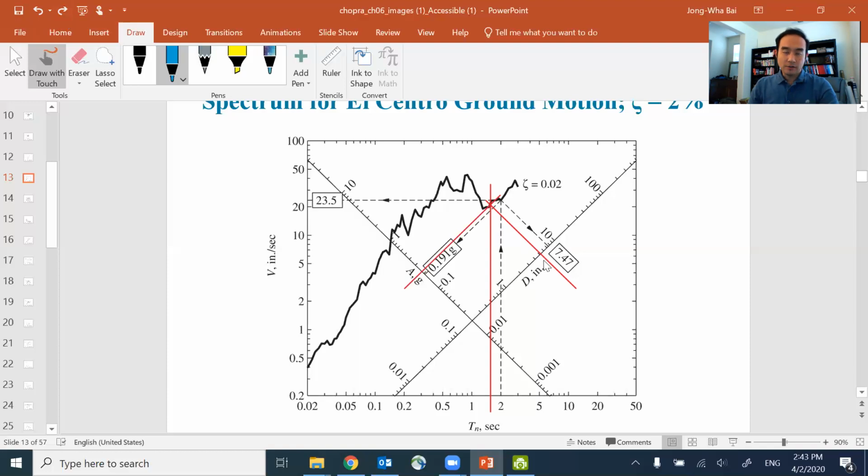So this 5-inch maximum peak deformation and 0.2 g as a spectral acceleration value was used in the previous calculation. Now, the period is changed from 1.59 second to 0.502 second, okay? So even though our structural system is stiffer, way stronger than before, let's see how that seismic demand is going to be affected or not.